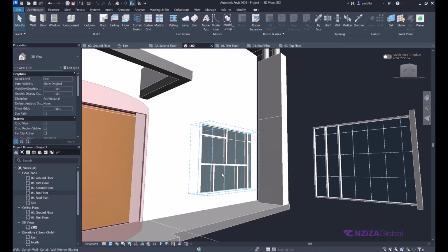Okay, now can you give the last part, how to add the members? How to add the members? Yes. Deselect it, then go to Mullion up here and cut it. Mullion, this one. Yeah, that one. Okay. Then go for all grids. All grid. Yeah. Then select the cutting. Don't have the internal one. So to put it outside. Yeah, you have the outside one.